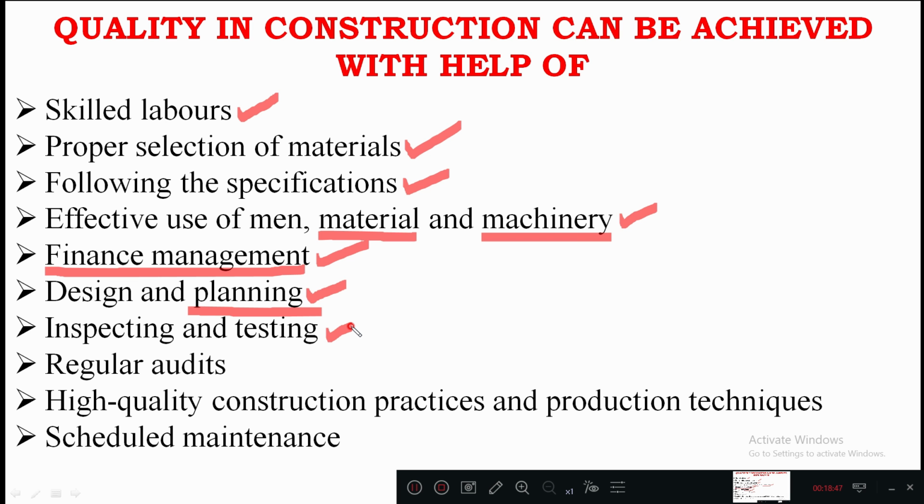And then in the concreting part, we need to check all the materials which are to be used in the construction of the foundation, check those material specifications, and along with that the SBC of the soil, etc. For each and every activity in the construction we need to follow inspection, and then regular testing will be there. So testing of the materials, whether we can conclude it's suitable for construction works or not.